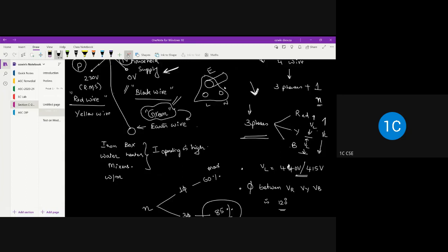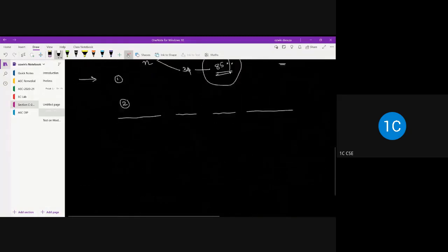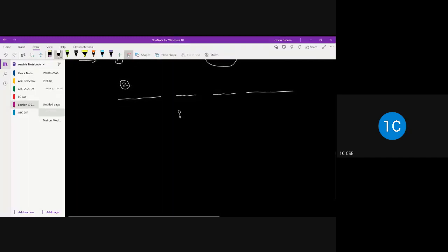So this gets into the wall socket. So wall socket will have 3 holes: the earth hole, line, and neutral hole. And this earth terminal of the wall socket is basically connected to the earth pit. Okay, so this is your earthing equivalent. Okay, so earthing is normally indicated by this symbol. Okay, this is called the earth symbol.